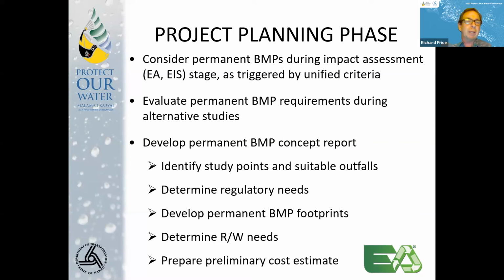We don't have time to design it and get it included in the bid package. And all of these can be avoided by some good project planning and upfront organization. For instance, when your geotech is out taking soil samples for the roadbed, they can also be collecting the soil samples for permeability analysis so that you can kill two birds with one stone, so to speak, and save having to send someone out again to do another analysis.